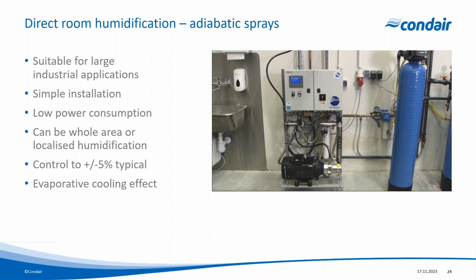And here you can see you've got a water softener in these blue canisters. So that's taking the calcium out and replacing it with sodium. That soft water then goes to an RO membrane and then a pump station, which is all contained in a single skid here. And we then pump water to the spray head.